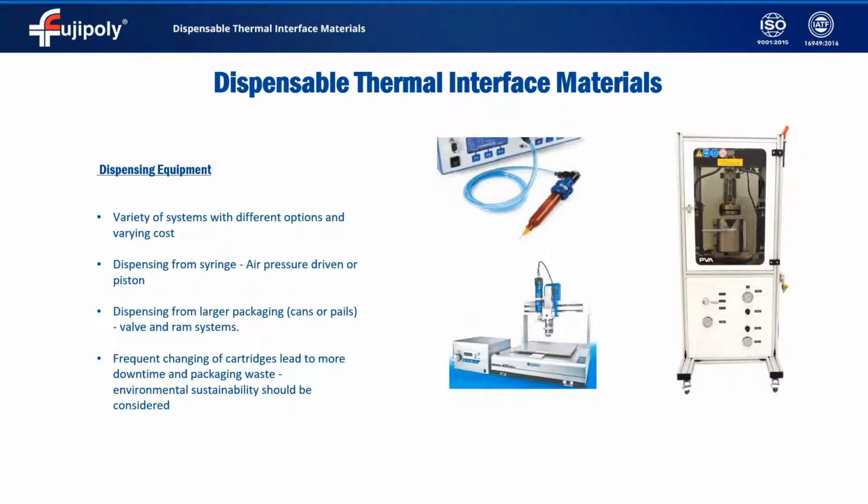The larger units typically use a separate hydraulic pump to feed material out of a pail over to the specialized valve in the robotic dispensing cell. Various types of tips or nozzles may be used when dispensing the material. The components are usually carbide to prevent damage by the abrasive thermally conductive fillers within the TIMs.